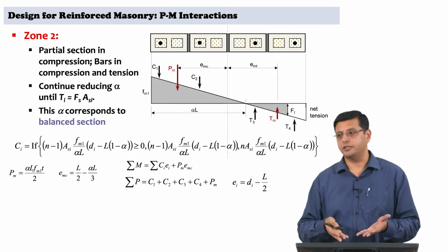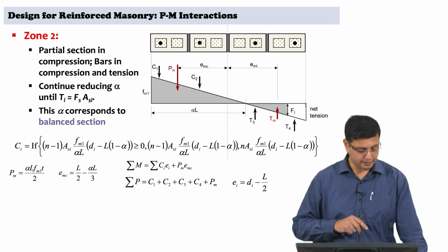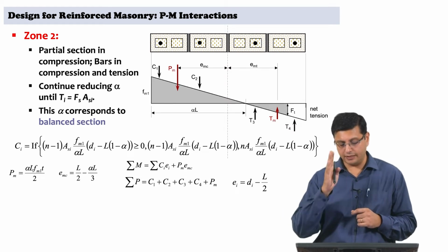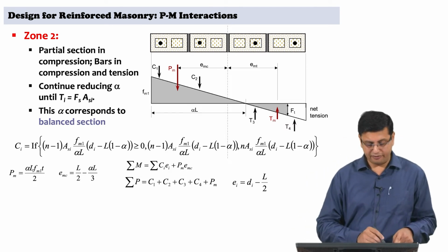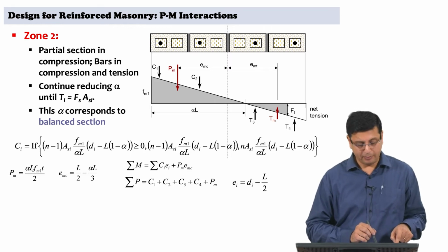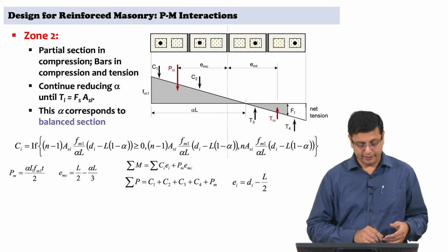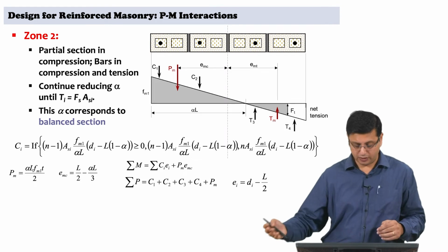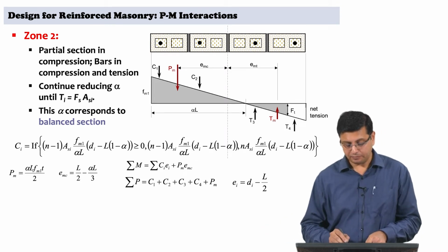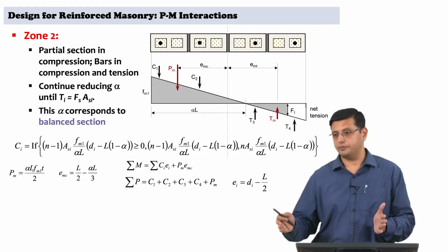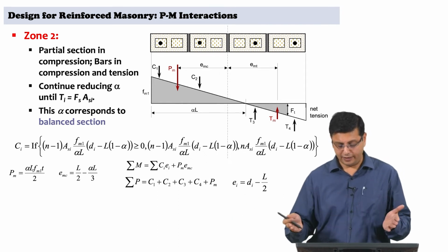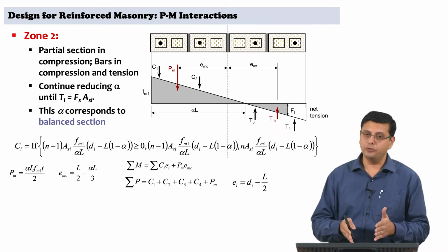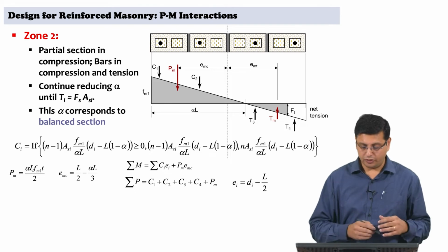That change you will have to make as far as the calculations of compression resultant, because the distribution of compressive stresses is triangular now. So, here you basically need to establish whether you are looking at a compressive force resultant or a tensile force resultant at each bar. So, you are checking if the earlier estimate of the compression force in the bar itself, n minus 1 into As I, is what we had seen earlier, into Fm2, that is the side which is in tension. So, you are checking with respect to the side in tension Fm2 by alpha L. Now, this alpha L is nothing but the length of the compressed zone, that is it is less than L, alpha is less than 1. So, as the wall starts cracking, the length of the compressed zone is less than the original length L, and therefore, now you are going to be using the value of alpha L instead of L in your calculations for the zone that is in compression.